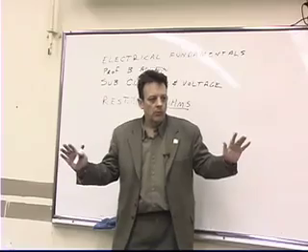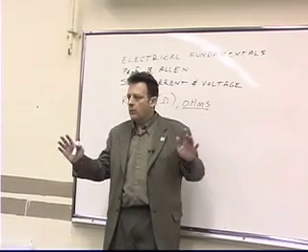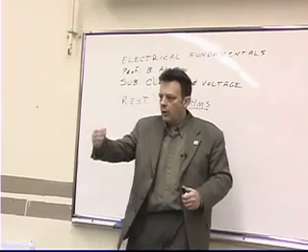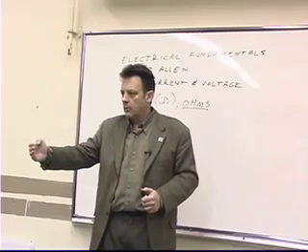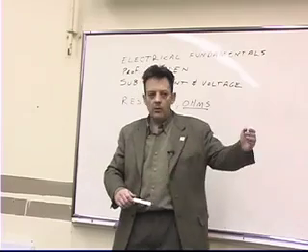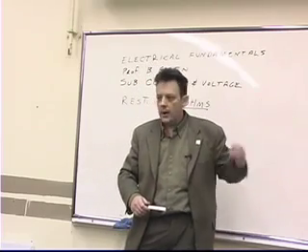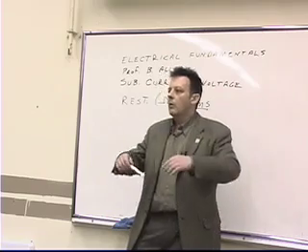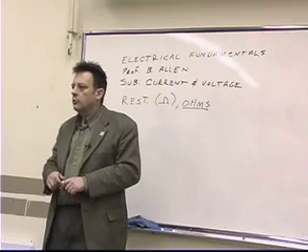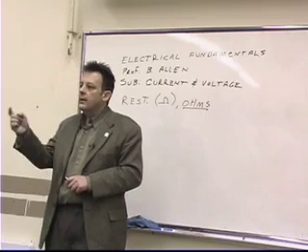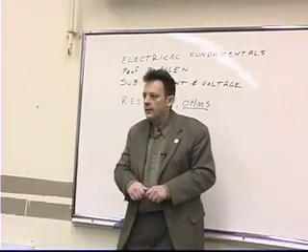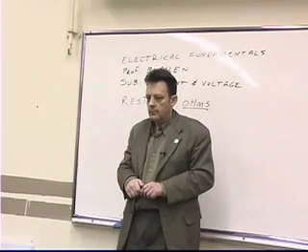Whoa! What do you mean down? How could it go down? If I plugged more hair dryers into the receptacle, how could my loading on my panel, where my breakers are, go down? Well, as we will learn, the reason that it goes down is because resistance is an inversely proportional relationship. In other words, we find it in the denominator of a fraction.